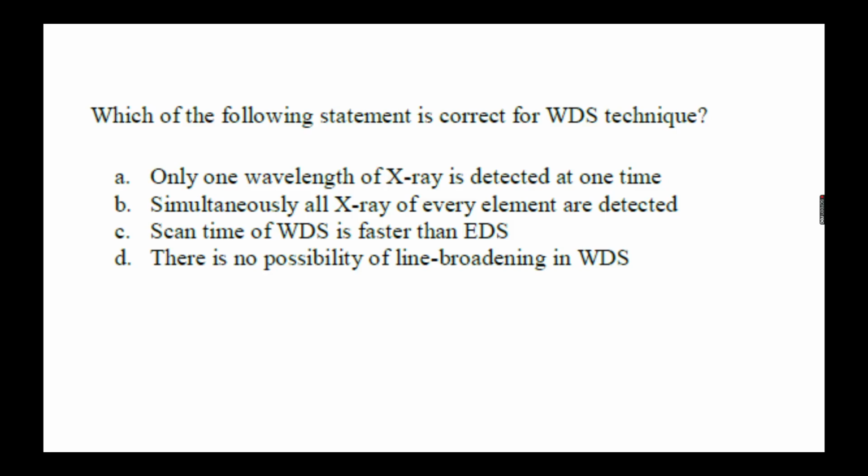Which of the following statements is correct for the WDS technique? Only one wavelength of X-ray is detected at one time. Simultaneously, all X-rays of every element are detected. Scan time of WDS is faster than EDS. There is no possibility of line broadening in WDS.